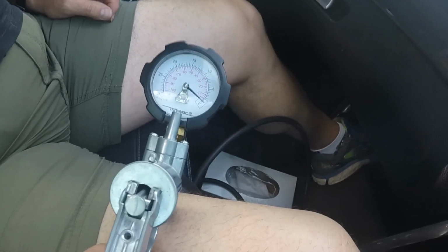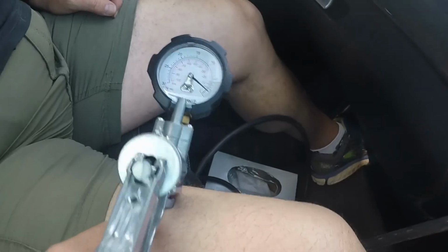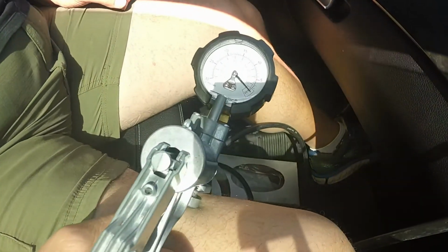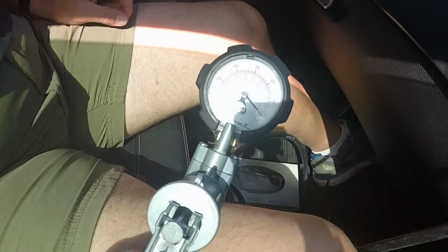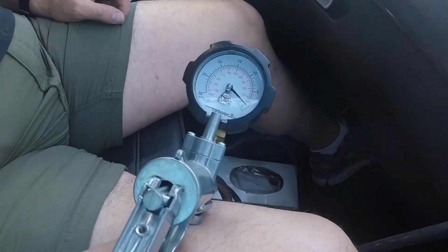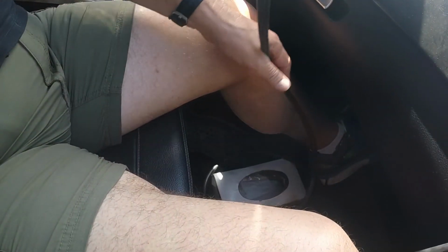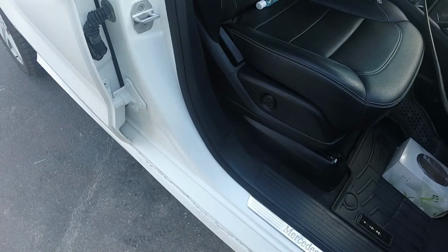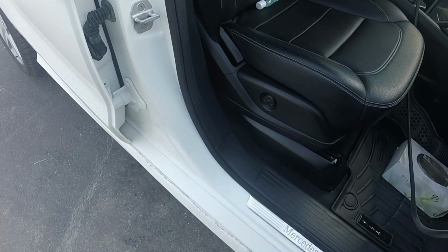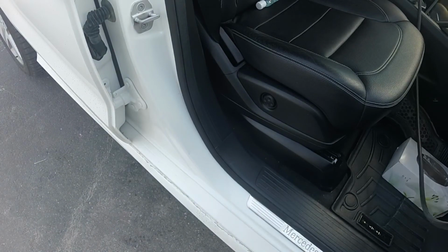Okay. And I'm going to assume that when the vacuum drops to 0, that's when the underboost code sets. So we have a problem with vacuum to the turbochargers on this thing. So what I'm going to do is get out and change my vacuum hose over to the vacuum side of the turbo so that we can monitor the electric vacuum pump to see whether it's supplying vacuum to this thing during the event or not. So just give me a second here. I'm going to switch the vacuum hose over, and then we'll road test it again and see if the pump can actually maintain vacuum during the event.